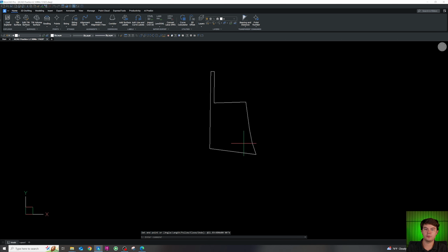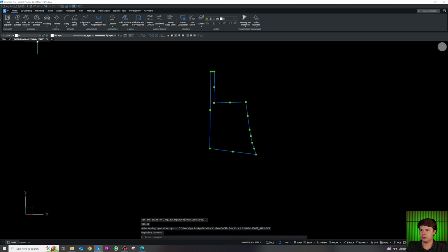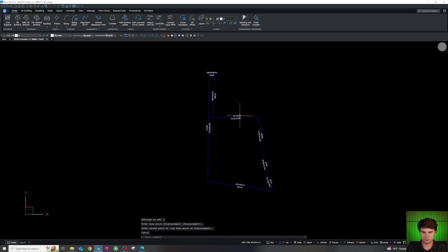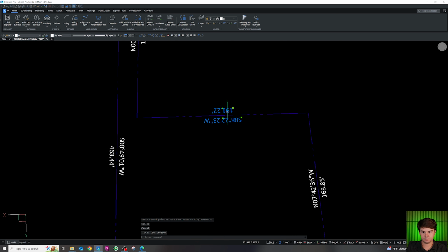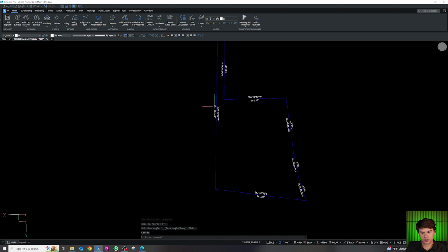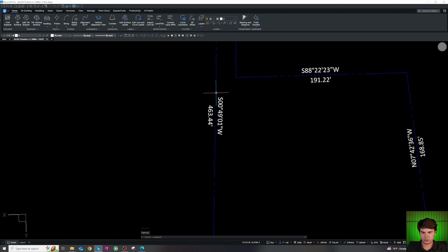Okay, now that we've got our property lines in, put these on the proposed property line layer, and I'm going to run LP. Now I've run LP, just make sure everything is straight. So I'm going to rotate this. And I'm going to rotate, actually, okay. Rotate this one.